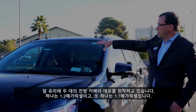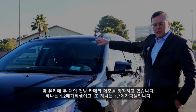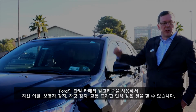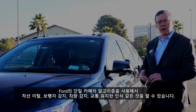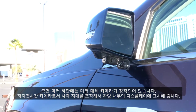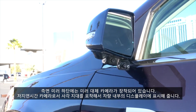So there's 2 forward camera demos inside the windshield here. One is a 1.2 megapixel, one is a 1.7 megapixel. They're running forward single camera algorithms such as lane departure, pedestrian detect, vehicle detect, traffic sign recognition. On the side here, under the mirror, is a mirror replacement camera, low latency camera, shooting back in the blind spot area with a live display inside the car.